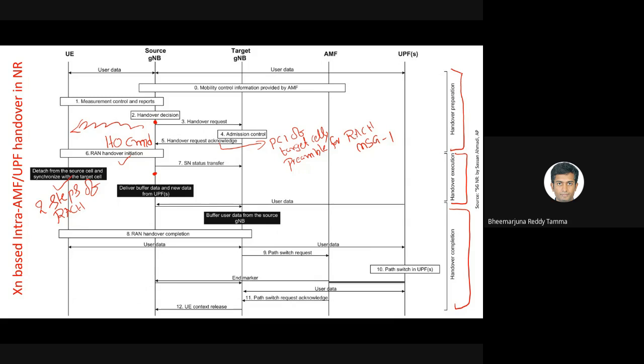And the user is really going farther away from the source gNodeB, the link will break, and again you have to restart the entire RACH procedure to reconnect the user to the network. Okay, that time it will start from the initial cell search, listening to the SS blocks and everything, and the ongoing call will be dropped. The ongoing PDU session or data session, whatever you have, is gone. Okay. Okay, sir.